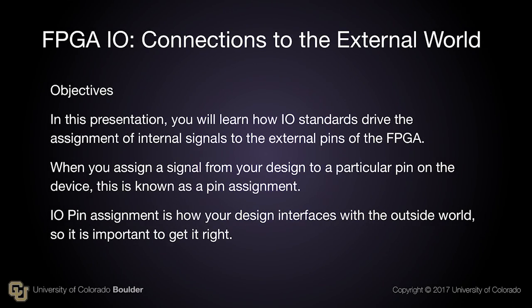In this video, you'll learn how I/O standards drive the assignment of internal signals to the external pins of the FPGA. When you assign a signal from your design to a particular pin on the device, this is known as pin assignment. I/O pin assignment is how you design interfaces with the outside world, so it's important to get it right.